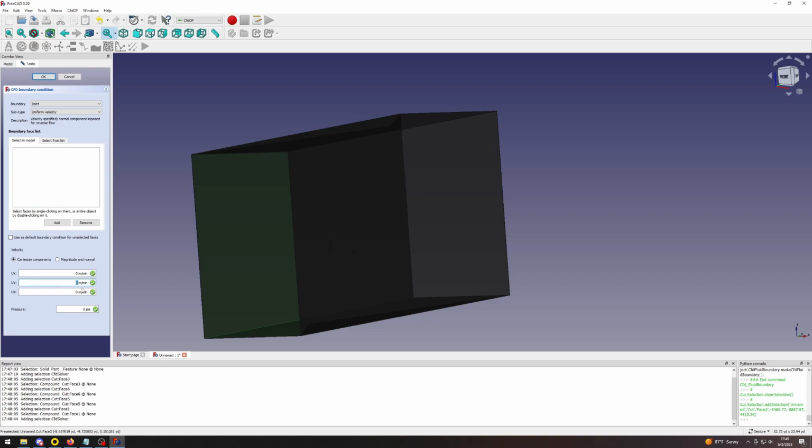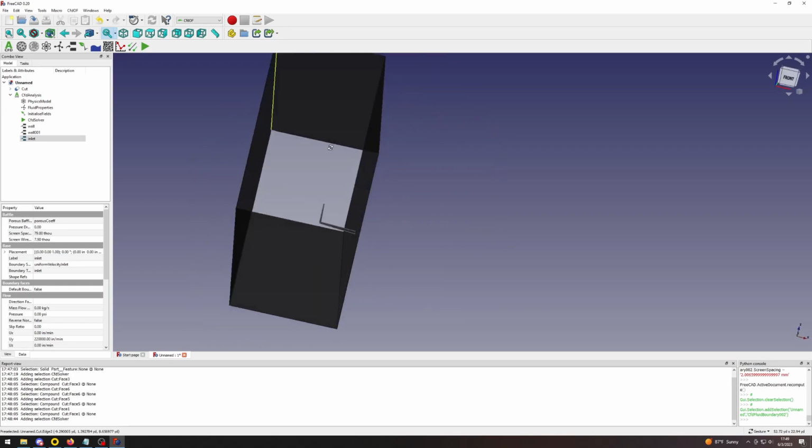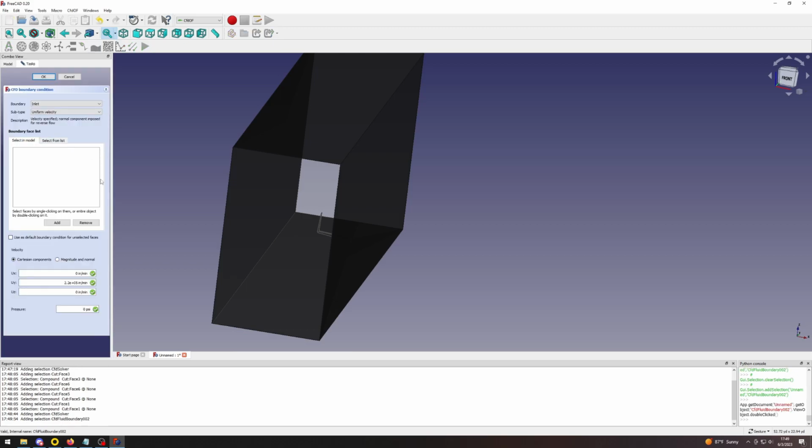So I calculated out, or for whatever reason, I picked 185 knots. And that comes out to 213 miles per hour, or 224,928 inches per minute. It's going to abbreviate that into 220,000 inches per minute, but that's close enough. And there we go. So that is our cruising speed of the airplane that makes sense for this particular wing. But you could test it at a variety of speeds and see how speed affects your aircraft. And now we're going to click OK. So now we have an inlet. That is where, well, we should. This is why I like to double check it.